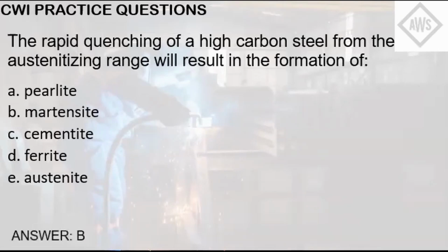martensite. Martensite exhibits a body-centered tetragonal structure which has high internal energy resulting in high hardness and tensile strength, but comes with low ductility and toughness. For the choices, pearlite forms at a slower cooling rate than bainite and martensite. Bainite forms at a slower cooling rate than martensite, hence with lower ductility than pearlite. One characteristic of bainite is that it is very difficult to see under the microscope.